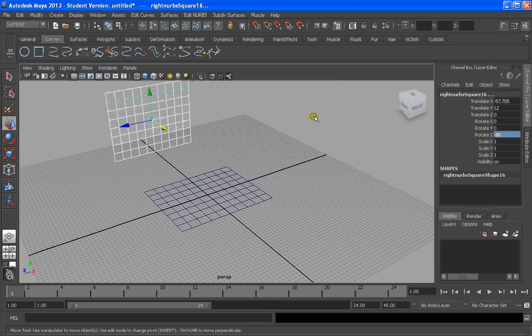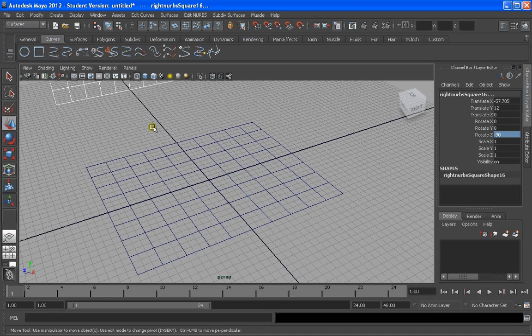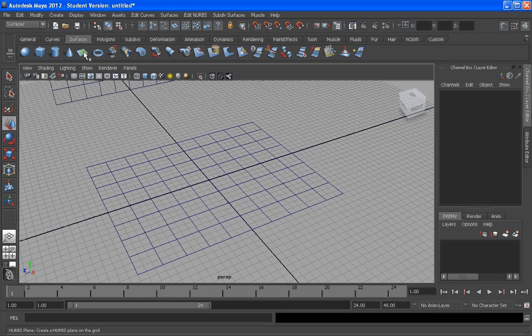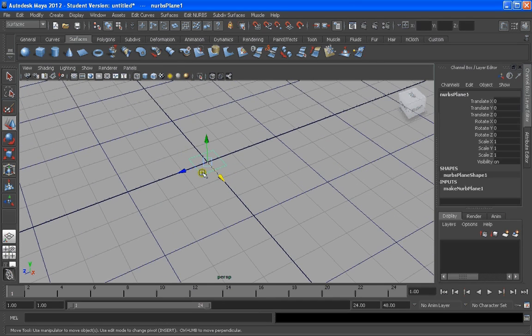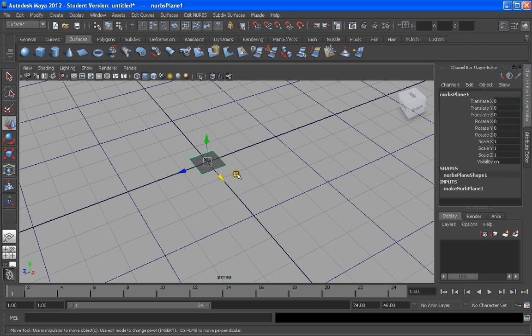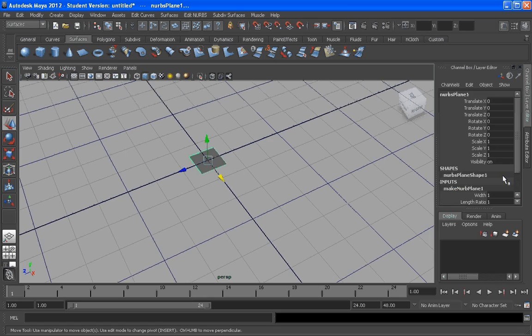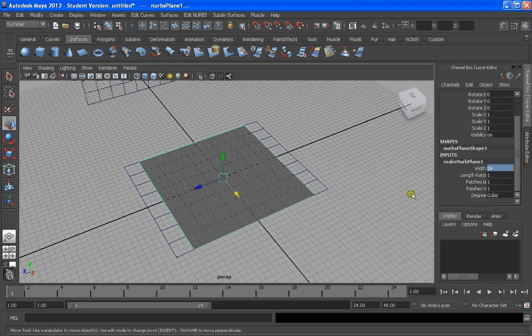I'm going to do the other grid that's going to be in this set for the front in a different way. I'm going to set first surface. Press that one. Remember, there's no interactive creation, so it sets a surface of 1, 1. If I press 5, you can see the surface. And now we can just go here to the attributes, to the channel box, and change the width of that box, and we can set it to 24. So it's actually exactly 24. And the number of U is going to be 8 and 8.